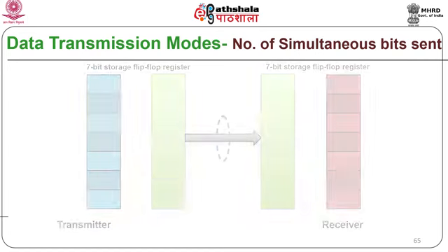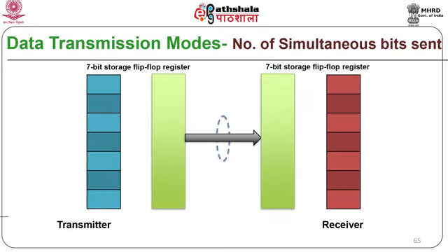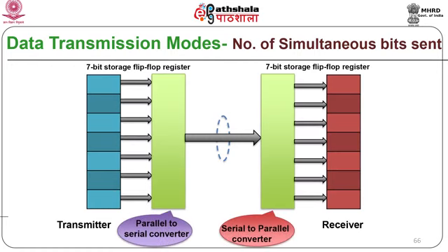In computers, digital data transmission between circuits is in parallel format. Therefore, parallel to serial conversion devices are required at the interface between the transmitter and the single transmission line. Also, there is a requirement of serial to parallel conversion between the single transmission line and the receiver. Such data conversions are made possible by shift registers.